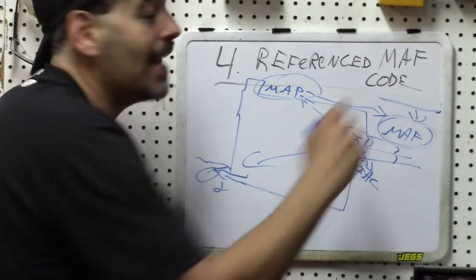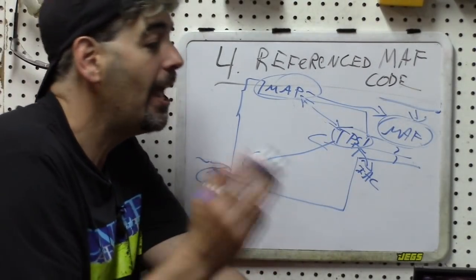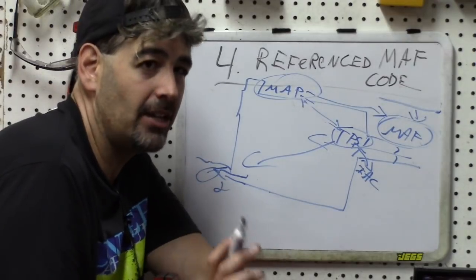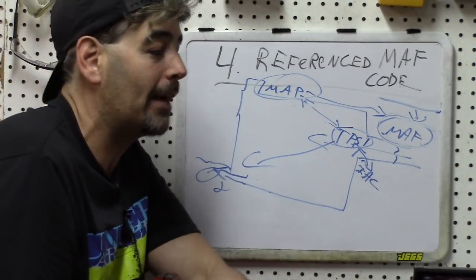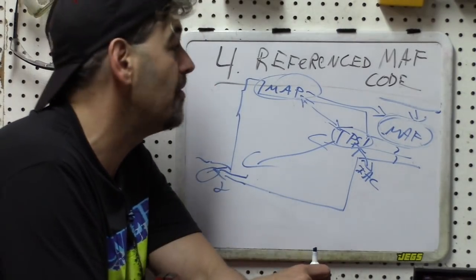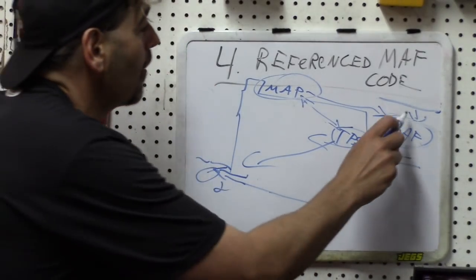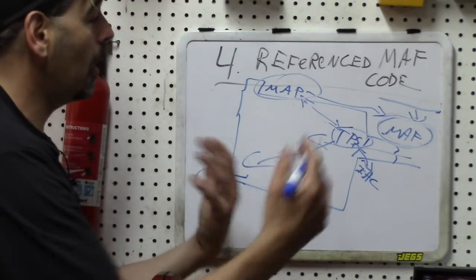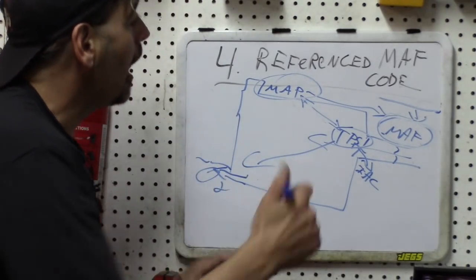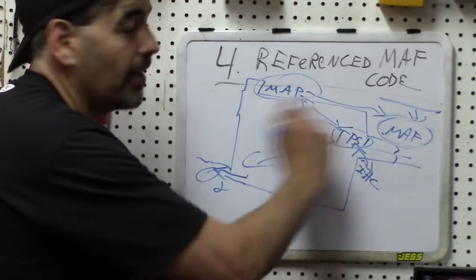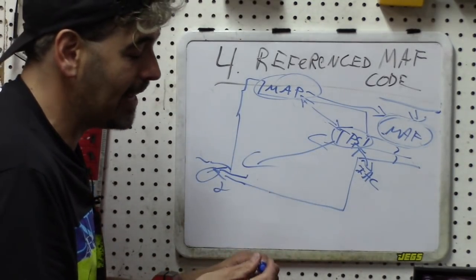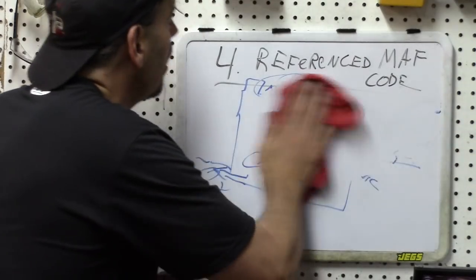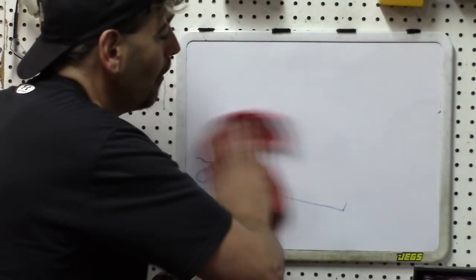Simply disconnect your mass airflow sensor. If you get a dramatic improvement in your symptoms, then maybe you might start targeting that a little bit better. Almost invariably, you will not, however. So that's another little trick you can do. But again, it comes from taking advantage of knowing how these various components are interconnected. So hopefully that'll help you prevent making misdiagnosis. And that will also go ahead and round out this series.